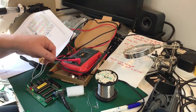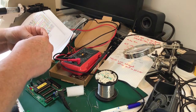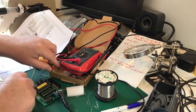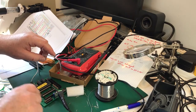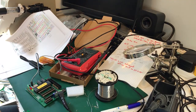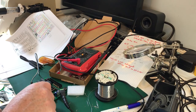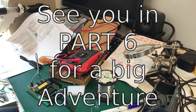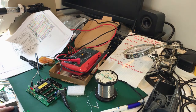But obviously we've no idea if the PIC will do anything, so we could, in theory, reset. It doesn't seem to do anything, but we'll need to see if anything's coming out of the serial port so we can talk to it, which means hooking up to the Max 232 layout and hooking up to a USB controller on a machine downstairs perhaps. So we'll knock the electronics workshop on the head and go and have a little try next to a computer. A slightly better computer than what I got in the electronics workshop.